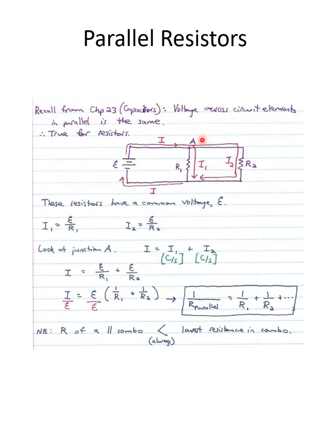Let's look at the junction that I've labeled A. The total current, I've labeled right here as I, is I1 plus I2. So many coulombs per second go into junction A. And those coulombs per second are going to be divided. Some of them are going to go through I1, some are going to go through I2. They'll eventually meet up again. So at this junction down here, it'll eventually become the full I, the full current. But as they divide up, we can see that I equals I1 plus I2.